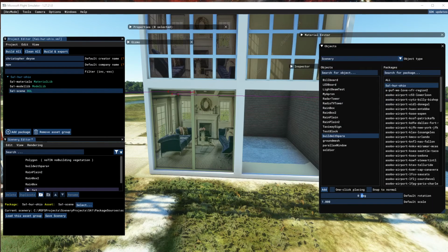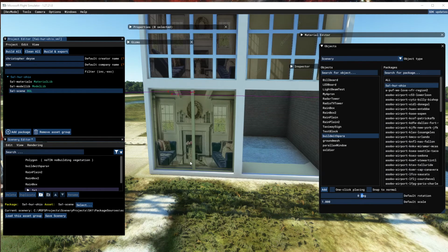So we'll open that up in Notepad++. You can't see it, it's off the screen, but I'm doing the same thing. Hit space, backspace, and then resave the GLTF. And it'll look like the room is not as deep as it used to be. See how that, I brought it, so I set the scale to 25% of the parallax, the plane size. So it looks like the back wall is closer to the window.